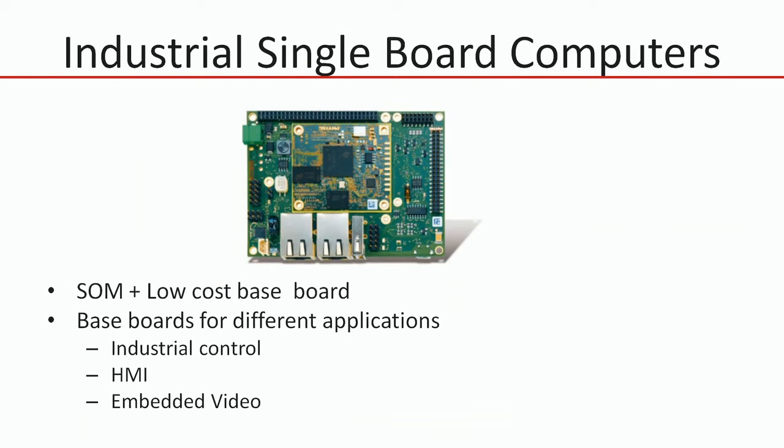In the last couple of years, Phytec have also produced some low-cost baseboards that are customized towards particular types of application, such as industrial control, HMI, or embedded video. And the module plus the baseboard are generally available at a low cost, around 70-80 euros. So again, these are very good development platforms if you have an application that fits one of these baseboards, and they're also suitable for serial production as well.